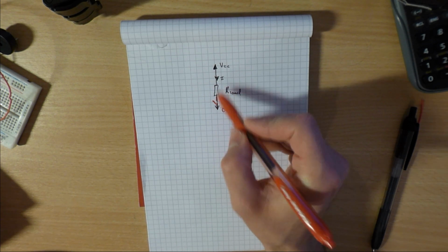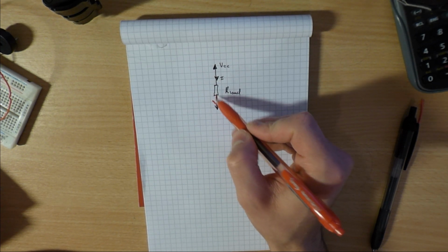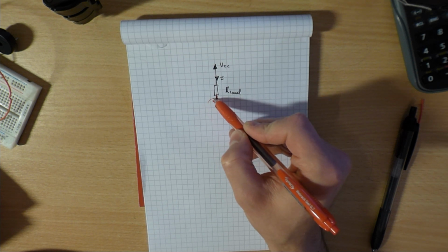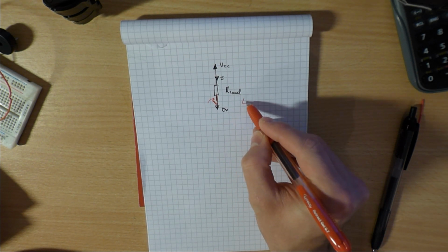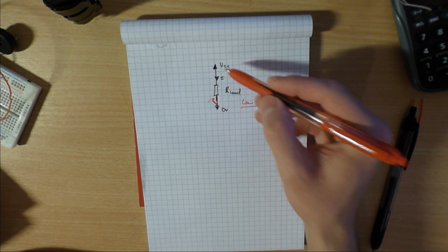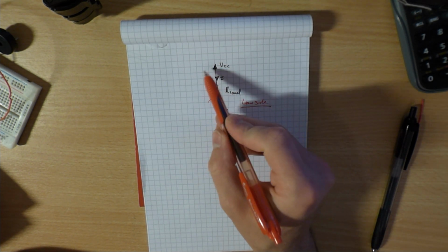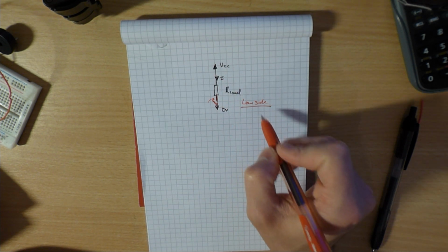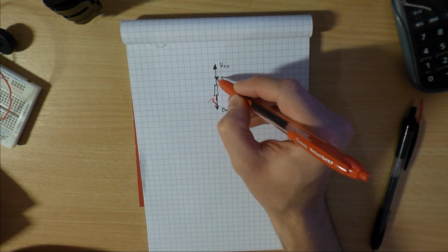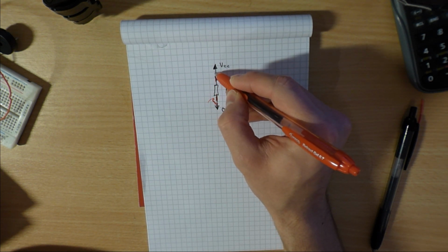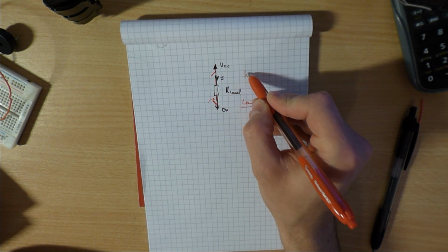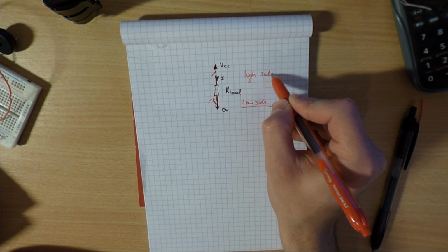Okay. Now we can control the current flowing through this resistor by turning this switch on and off. And this is on the low side of the power supply, which makes it low side switching. Likewise, if we put a switch up here, like this, it's called high side switching.